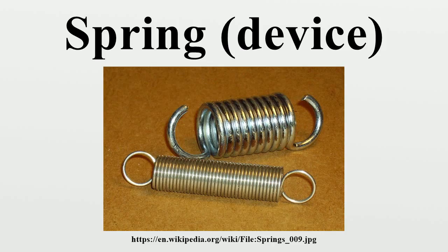Zero-length springs. Zero-length spring is a term for a specially designed coil spring that would exert zero force if it had zero length, if there were no constraint. Due to the finite wire diameter of such a helical spring, it would have zero length in the unstretched condition, that is, in a line graph of the spring's force versus its length, the line passes through the origin. Obviously, a coil spring cannot contract to zero length because at some point the coils will touch each other and the spring will not be able to shorten anymore.